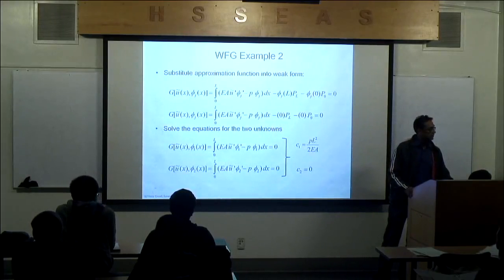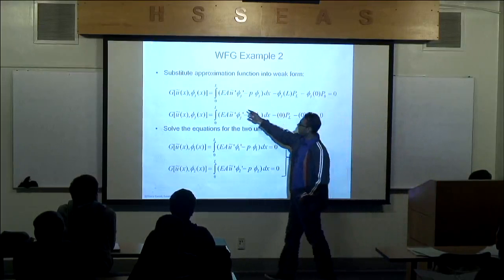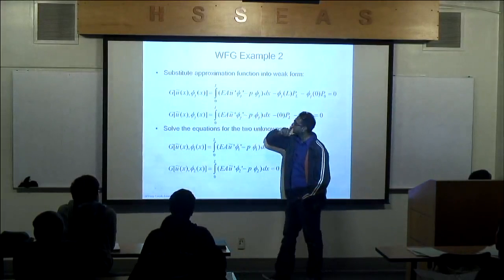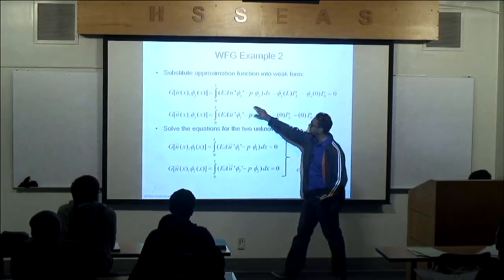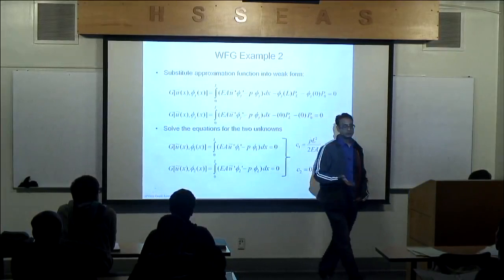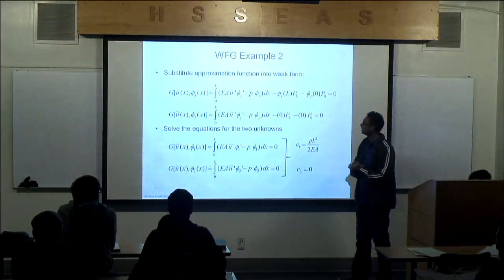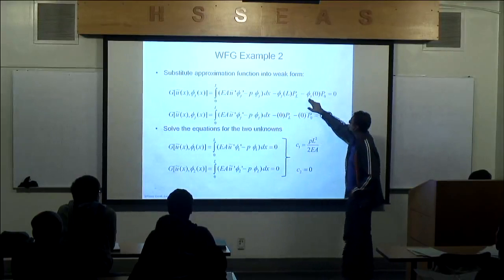In this weak form, I'll substitute in for the weight function. I'll select the basis function, right? For u, I'll put the approximation function in there. So what I've done is substitute what u tilde is, which was given in the previous slide, which is quite long. It's not short. And then boundary conditions become phi j at L and then phi j at 0.